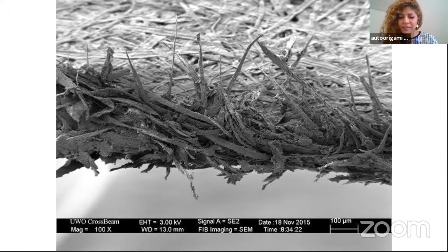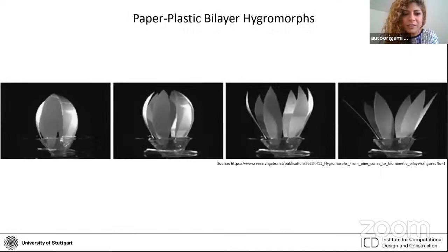As you know from Tiffany's workshop, cellulose is what makes wood structures or our 3D printed structures hygroscopic, enabling them to absorb moisture from the environment and change their shape. The same cellulose is in paper, so we can use normal paper to create similar hygroscopic structures, meaning structures that can open and close, or bend, in response to the moisture in the environment.